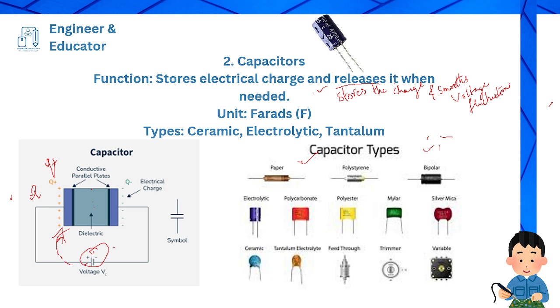The capacitor offers low impedance to AC and high impedance to DC. Due to this property, capacitors are used to couple AC signals from one circuit to another and to block DC signals. If we have to block some DC signals in a circuit, the capacitor provides high impedance to DC. So, in order to block DC, we make use of a capacitor. They are widely used in signal generation, tuning, filtering, and so on.